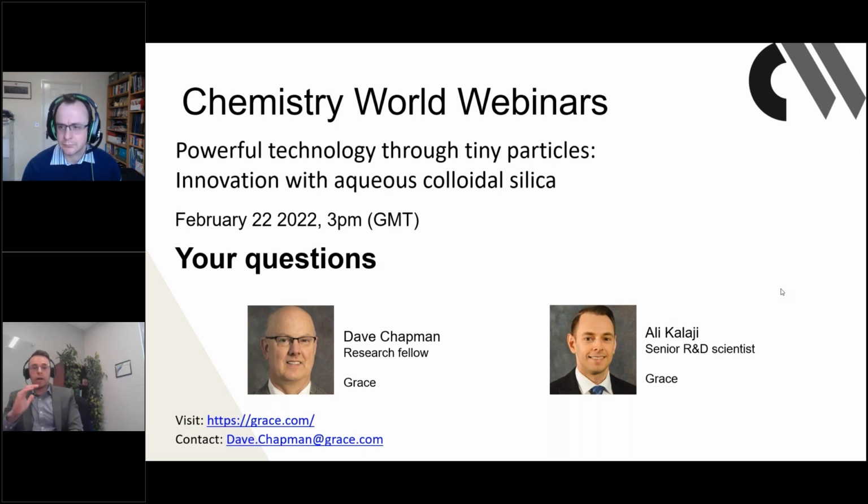So if you have a high concentration of, say, calcium 2+ or a lot of sodium chloride in your system, then there's always the risk that you're going to completely destroy that electrostatic repulsion, and that your particles will aggregate. Now, sometimes you might actually want to do that depending on your application in a certain step in your process. But in general, when you're just storing it or just starting to work with it, trying to dissolve it into your system, it is important to consider pH and the ionic strength of the system.